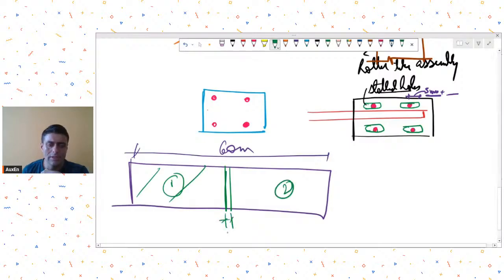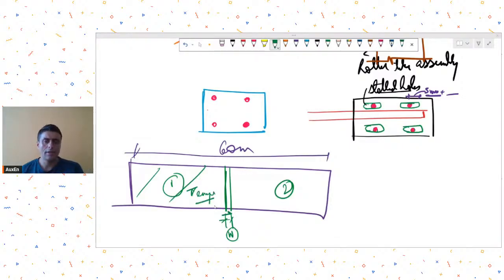So this is the width of the expansion joint that you have to provide. These calculations are especially important for temperature loads. In temperature, you can calculate the expansion that is happening, and then accordingly you can work out this gap that you have to maintain.